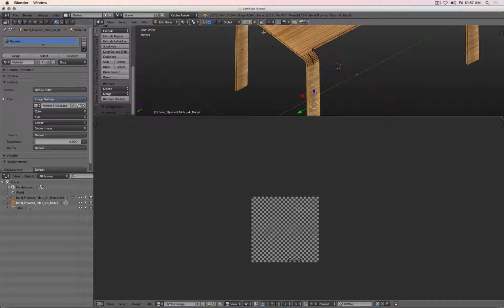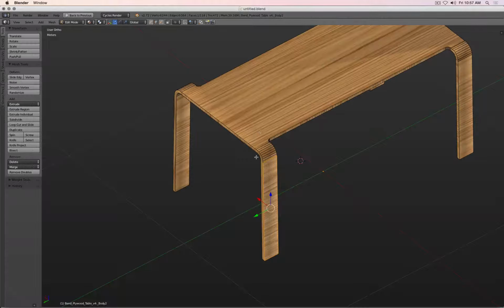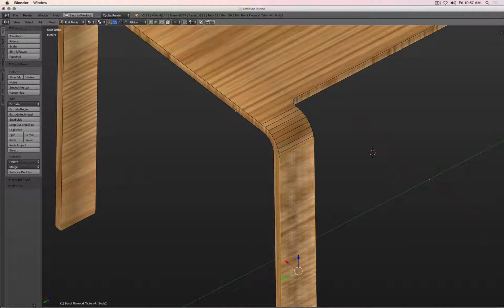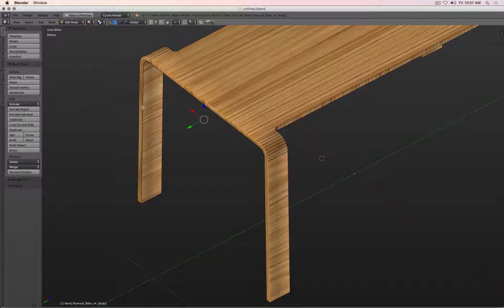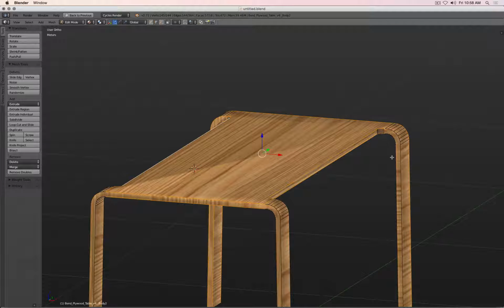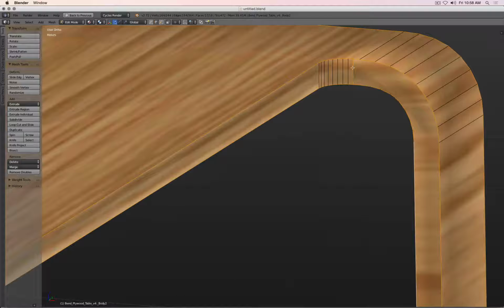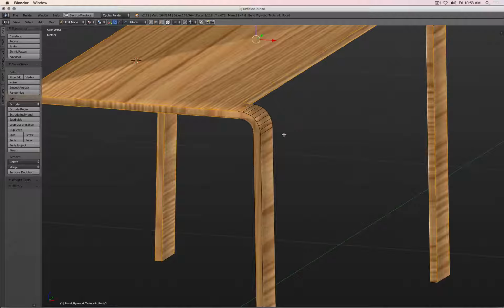The main reason for that is the following. I switch to edge mode, and then let's see if I can select those edges. So Shift and Alt to select a loop. Here I just have to deselect this edge, and there's a little offender.